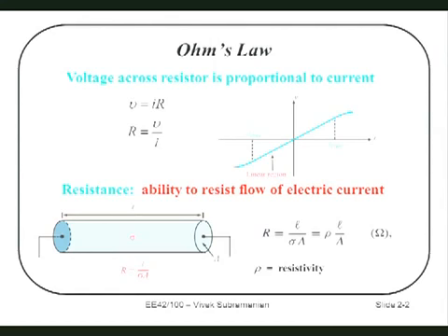They're in parallel with each other. So it's like having a wider road. There's more space, so you actually get a lower resistance. That's why we end up with this rule, which says the resistance of a rectangular structure is equal to rho, the resistivity, times L over A.